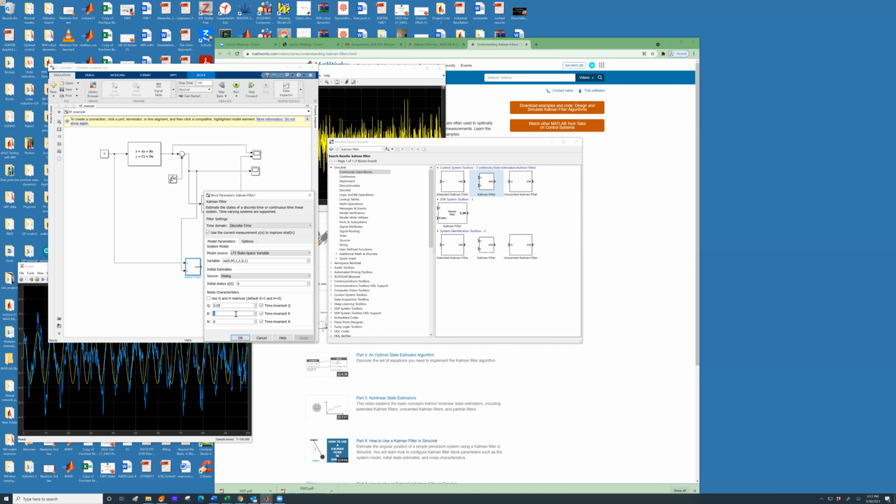You capture that varying signal and find the standard deviation, and that gives you the measurement noise. So please note, there are two noises. One is the process noise and one is the measurement noise. Q is the process noise and R is the measurement noise.